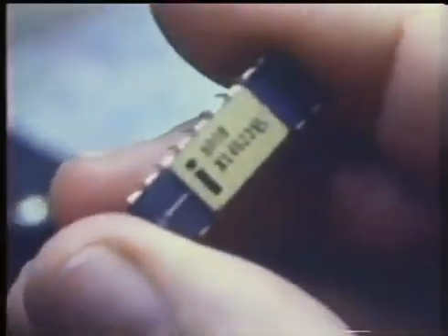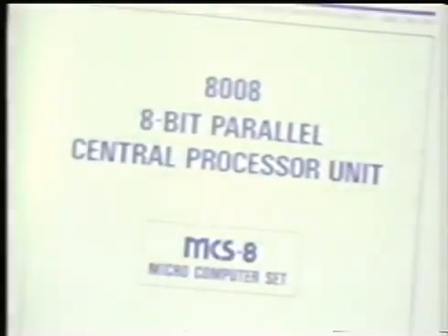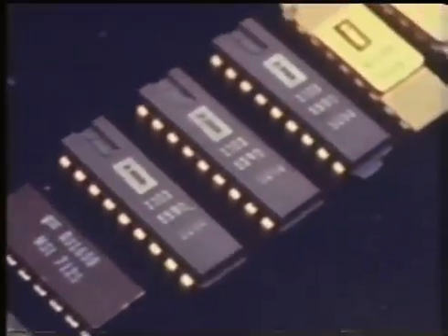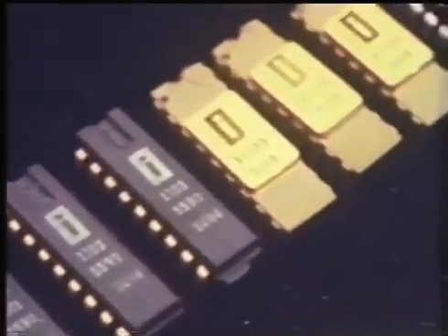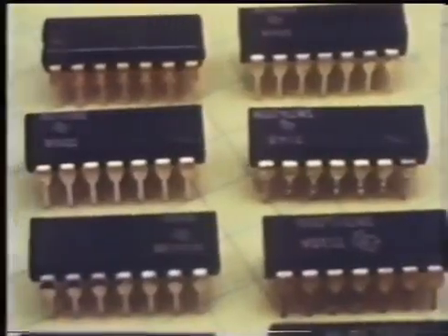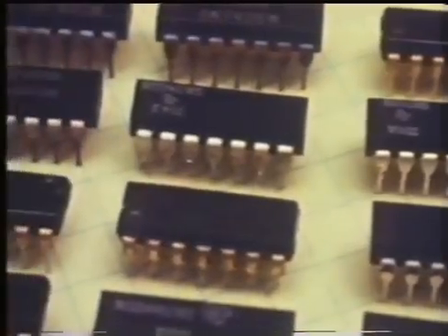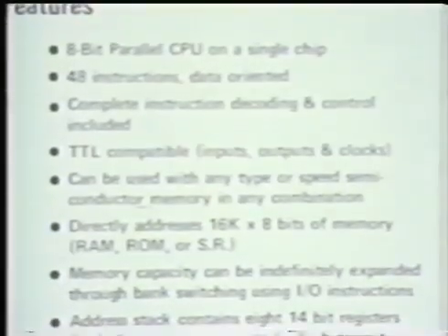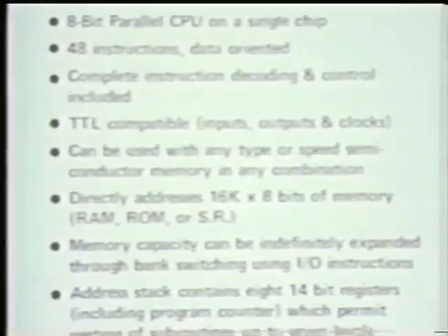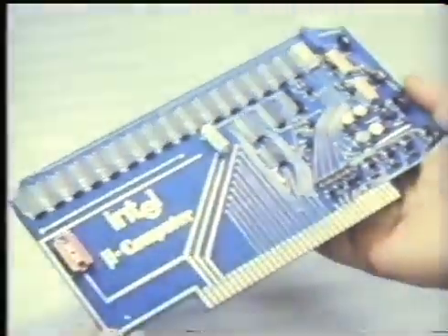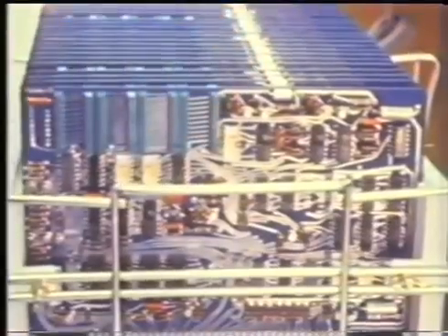We are also producing an 8-bit CPU, which works with standard memory elements, such as the 1103, 1101, 1401, 2401, or 1301 memories. This MCS8 system uses TTL devices to interface with memory circuits and has the ability to handle larger amounts of memory and do faster data manipulation. But the MCS4 is unsurpassed for small size and lowest cost.